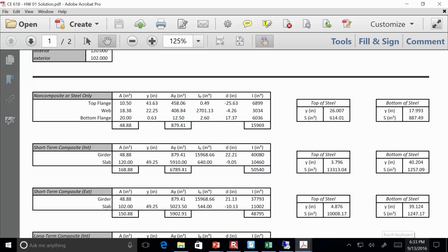The second thing also is, again, labeling. There were a lot of instances where the data followed, and then we had to do another section, so we'll just throw another little cell off to the side and put another effective flange width. That's fine, but later on, when you really have to go back and reference some of these values, where you need section moduli for the bottom flange on all these different sections, if it's not well labeled and well organized, then it'll create problems down the line.